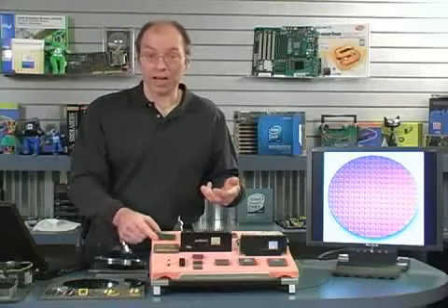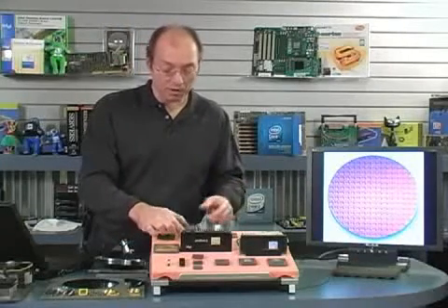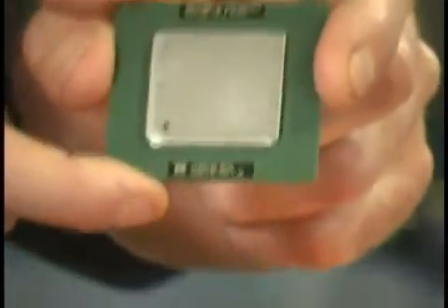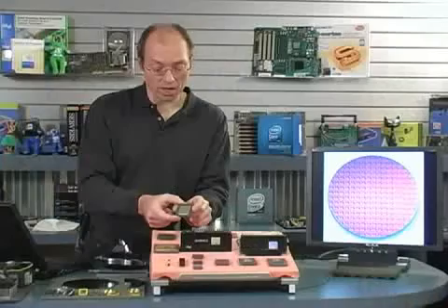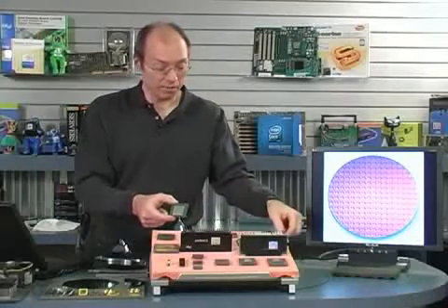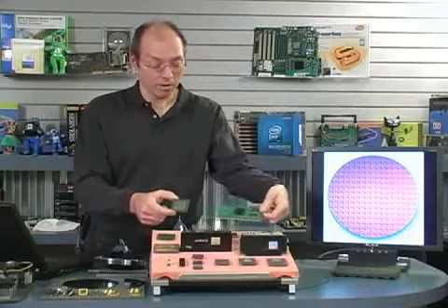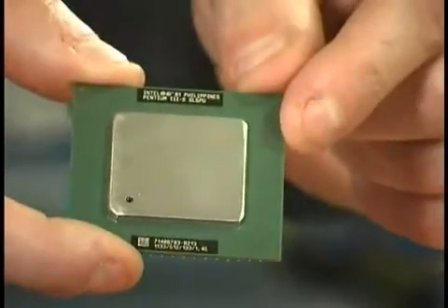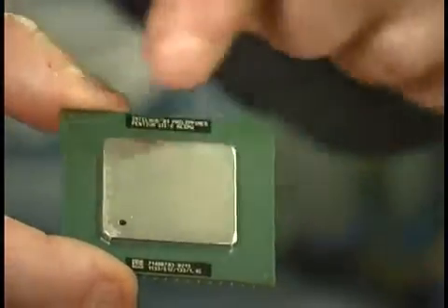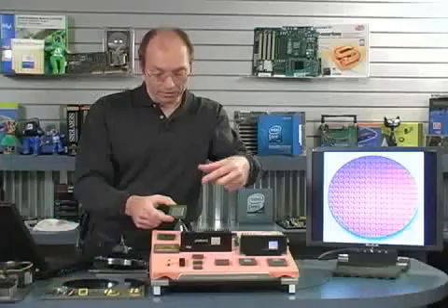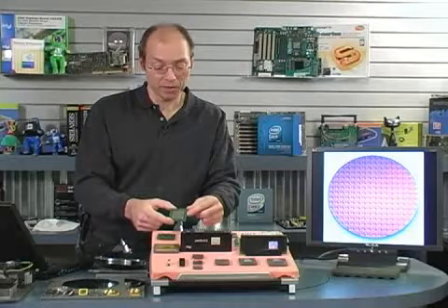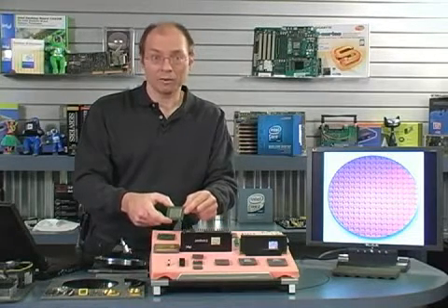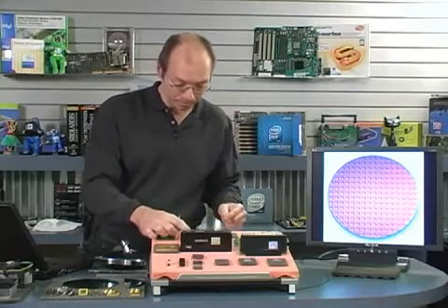So in more recent designs, both Intel and AMD have put covers over the processor die. This is an example of a Pentium 3 that has a couple of changes. Number one, the level 2 cache, which used to be separate chips. These are both Pentium 3s here. The level 2 cache is now built into the processor die, and then the die is now covered with a metal heat spreader. And they call this a heat spreader because it helps spread out the heat. It gives more surface area for the heatsink to attach to and dissipate the heat from the processor. Also protects the die, the raw silicon die, from any kind of damage. So these are much more durable.